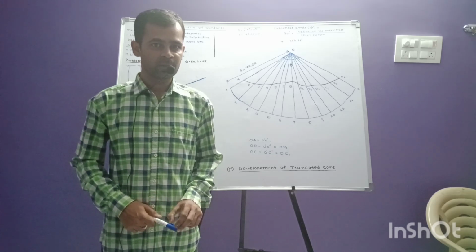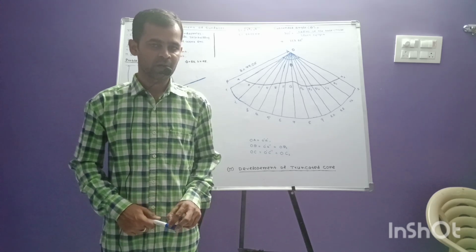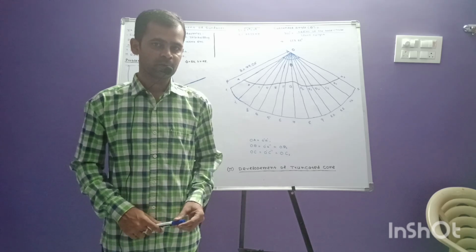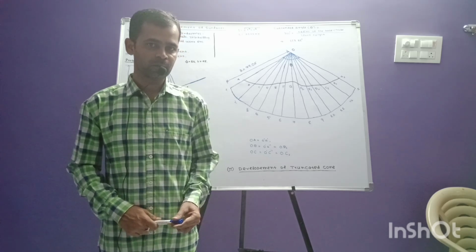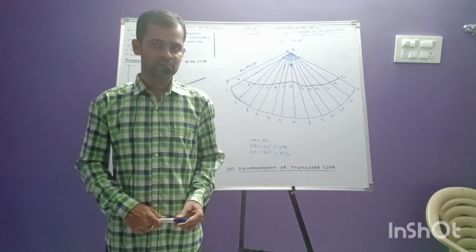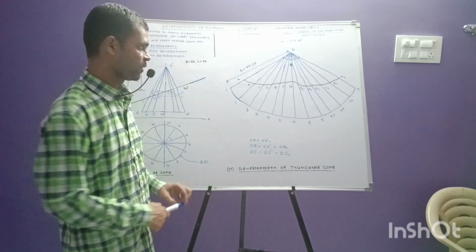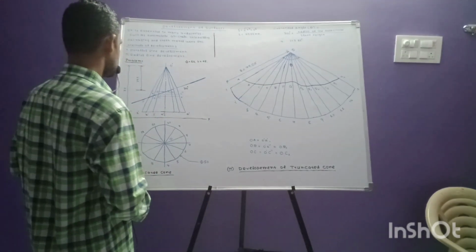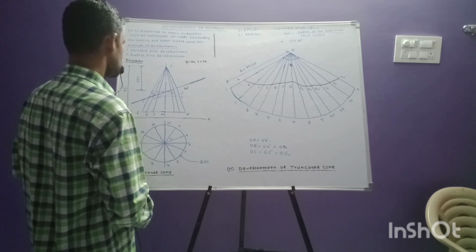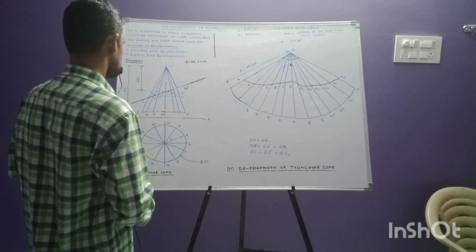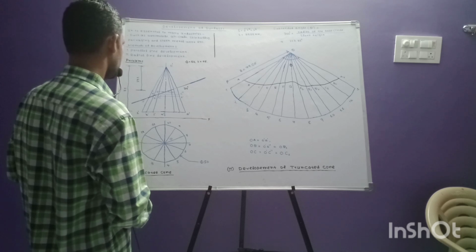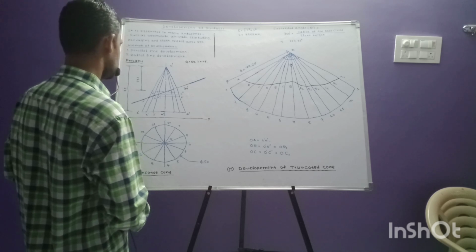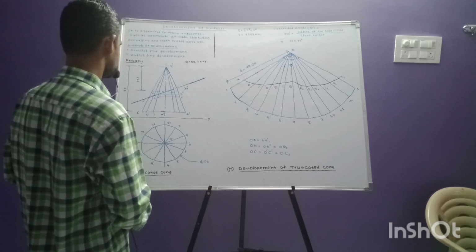So the plates or sheet metal are cut to the development diagram and they are made to the desired objects. So like that in sheet metals, boilers, chimneys, funnels, bins, so these kind of objects can be made by making use of development diagram.